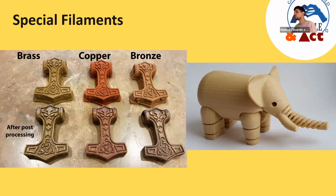Now, those metal filaments work with most 3D printers, not the cheapest ones on the market, but if you pay a little bit extra, you can find a 3D printer that prints metal filaments. Most of them are PLA based, so as I said, they are 80% metal and almost 20% plastic, so you can liquefy them in order for them to be 3D printed. But it is very easy to polish and post-process them.